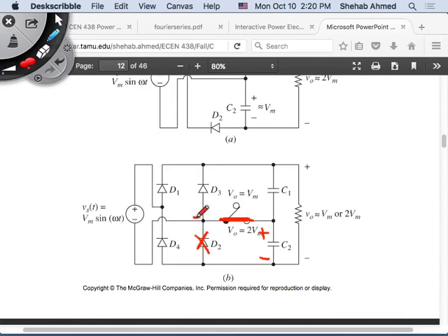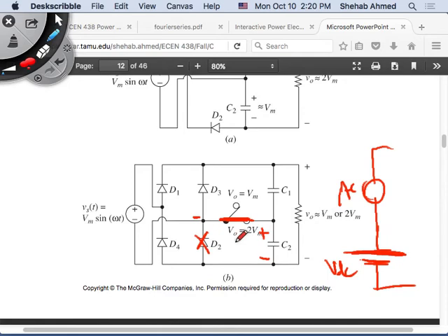The negative terminal of the source would be more negative than what? At C2? Yeah. But remember, this is a capacitor, so it will maintain its voltage. So it's like doing this. I've put now a supply here. It's like putting a DC source, VDC, and an AC source in series, right? And now you have your other circuit.